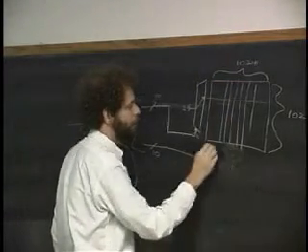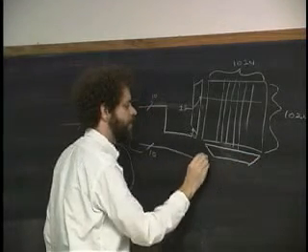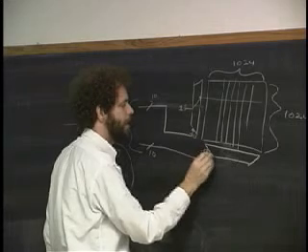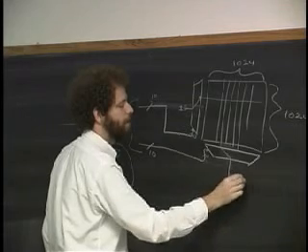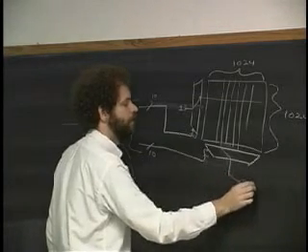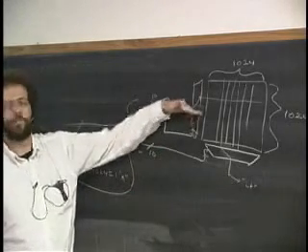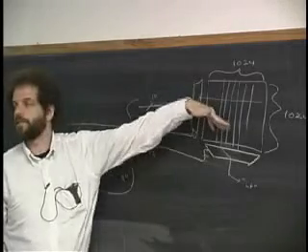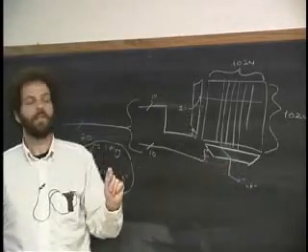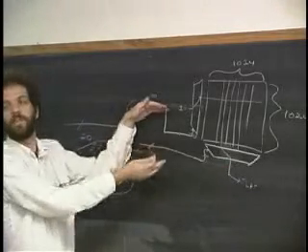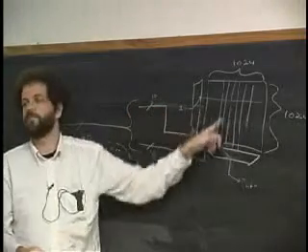And what I'll do is I will have a selector down at the bottom. And I'll take my 10 bits and I'll put those into there. And that will choose one of the 1,000 different columns, and out will pop the bit that I want. The bit that I love, okay? So these 10 bits will be used to choose the row. And once we energize the row, the 1,000 bits that are on that row will come down. And then we'll choose which column we want, and that'll get us 1 bit. And there are 2 to the 10th times 2 to the 10th, or 2 to the 20th, different possibilities of choosing a particular bit out of this matrix here.